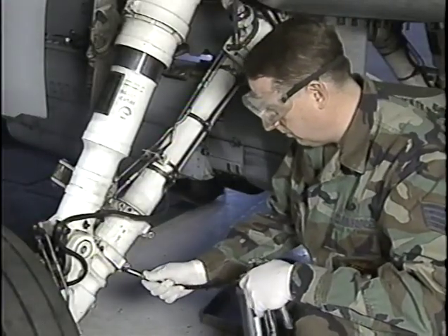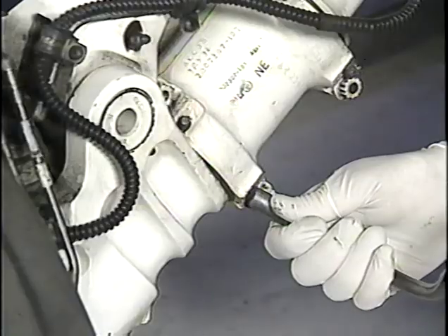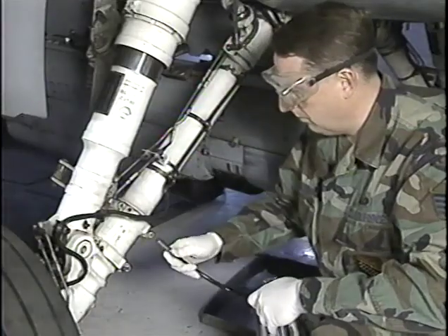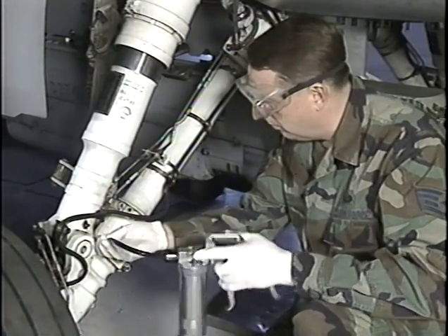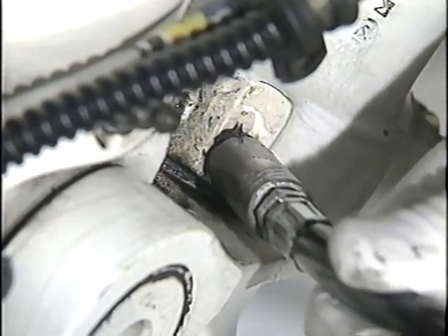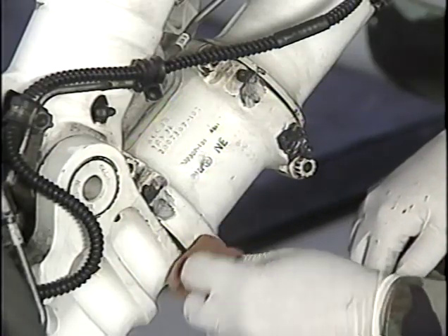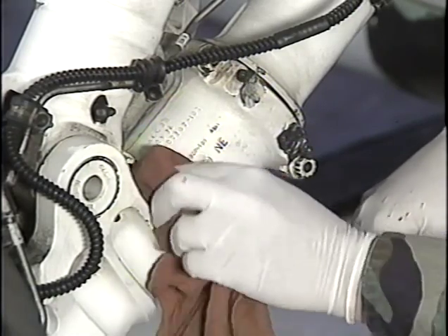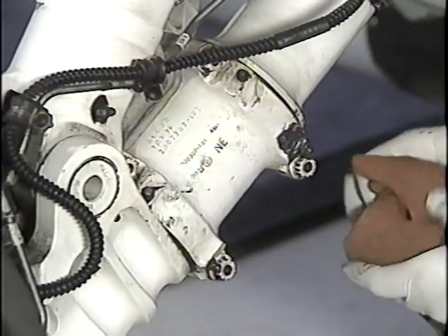Next, you must reapply the lubricants and greases to the required components. This aids in preventing wear, displacing water, filling airspace, and providing a basic barrier against corrosion. Always refer to the applicable tech data to ensure nothing is missed. Excessive grease around a fitting or lubrication on a hinge assembly should be removed to prevent the buildup of dirt, moisture, and other debris that can promote corrosion.